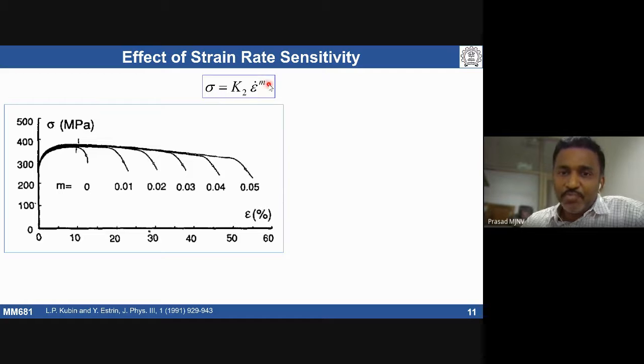If m is positive, for example, here is how the stress strain curve of a material changes as a function of m at room temperature. If we assume a material is showing increasing strain rate sensitivity, one can expect the ductility to increase at lower temperature. Even a small increase in the strain rate sensitivity m value, people have seen, gives some materials increased ductility.